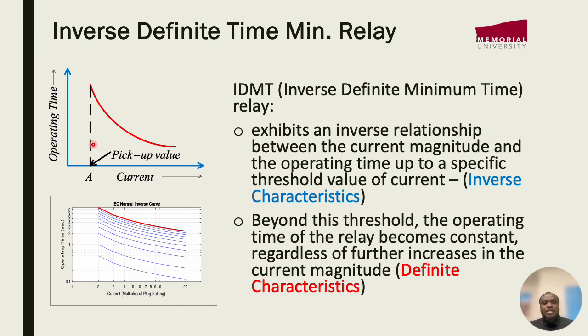So irrespective of the magnitude of the current, at a certain point the relay would react at a constant time period, and that's the beauty of this relay.